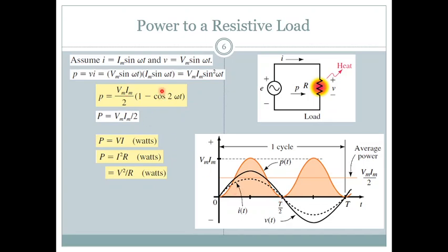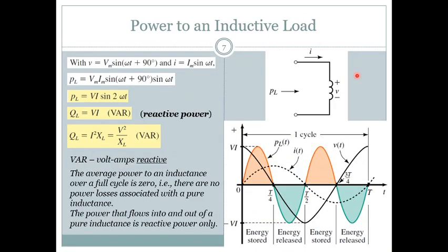However, as you can see from this equation as well as in this diagram, the total power is positive, meaning that the resistor has only active power component, right? There is no power component that is returning, meaning that reactive power doesn't exist in the resistor. So it actually can generate heat, or energy can be transferred.